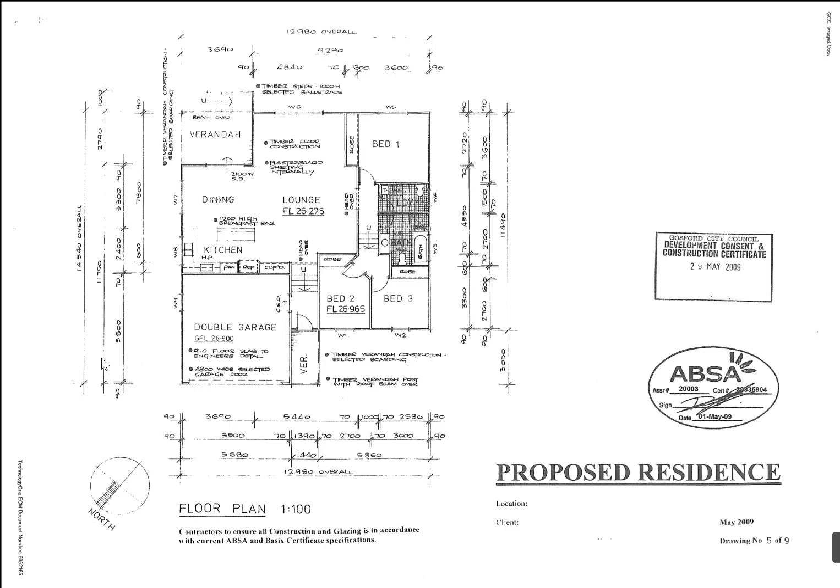Okay, that's pretty much about it on the drawings here. I think we'll go and have a look. Oh, no, beg your pardon. What we'll do, look at the windows. What we would normally have is door numbers and window numbers. So here we've got window 1, 2, round the side, 3, 4, 5, 6, and so on, round to window 9 in the garage. We don't have window widths here. What we would then expect is that they would show up in the elevations, or maybe on a window and door schedule. And I don't know if we've got one of those in this set of drawings, but we'll find out.